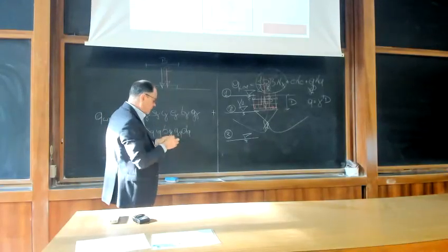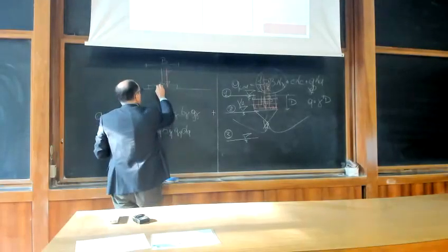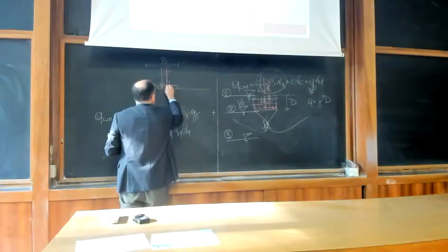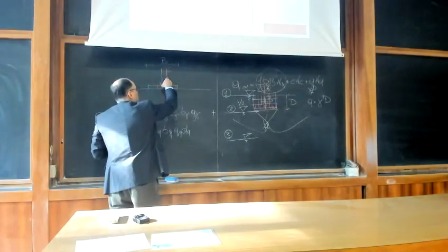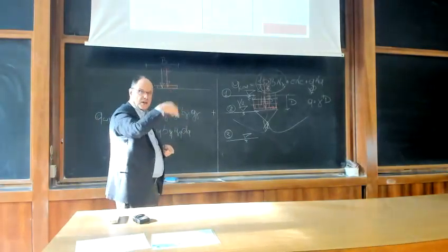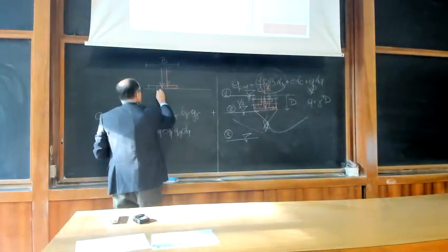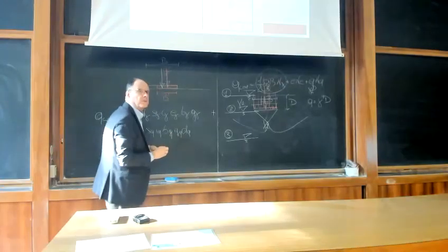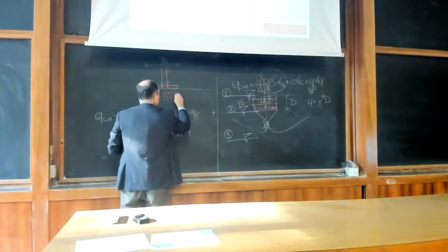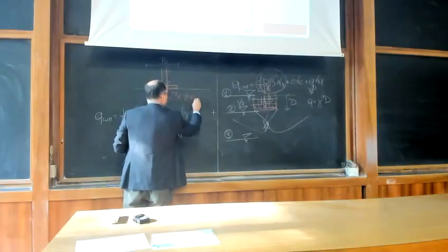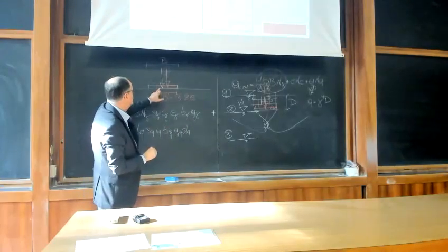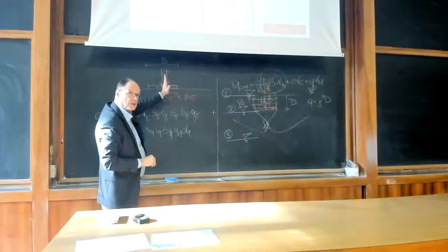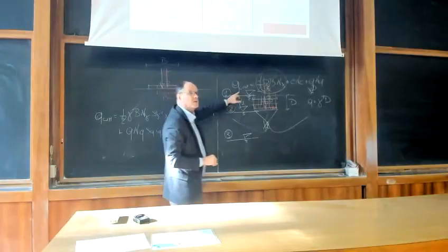Meyerhof suggests, well, why don't you consider a footing of reduced breadth, like this, for which the vertical load is centered. Now you have a reduced breadth B dash, which is B minus 2E, twice the eccentricity, for this footing the load is centered, and you can then apply this expression.